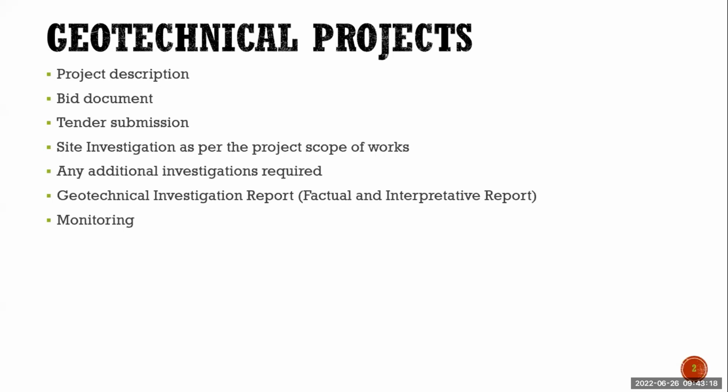If the engineer has geotechnical knowledge, he can define what geotechnical tests need to be performed on site. So let us say we talk about how many boreholes are required, how many trial pits are required, what tests need to be done and how many tests. This will be a bill of quantity. This will be compiled, along with which standard they have to follow. Everything will be in the bid document.